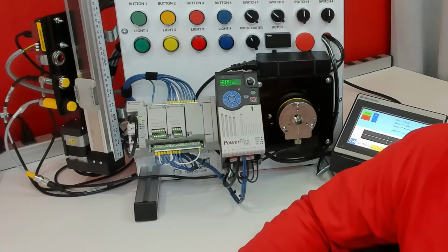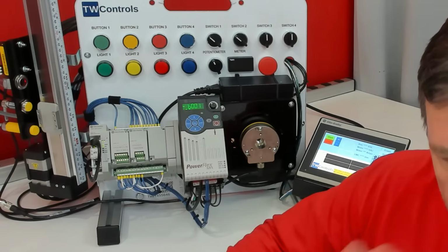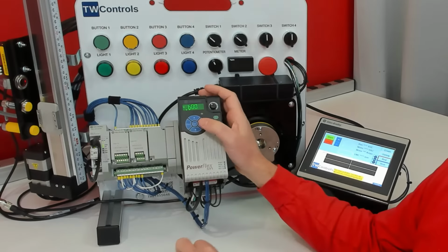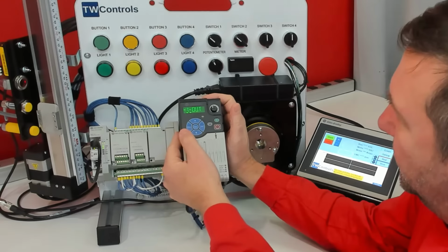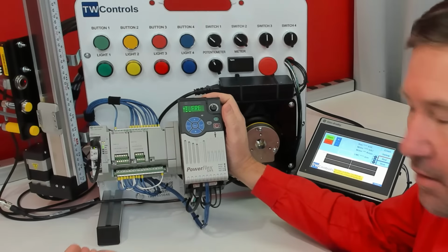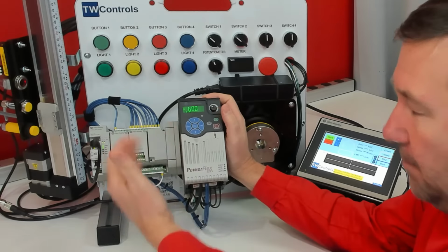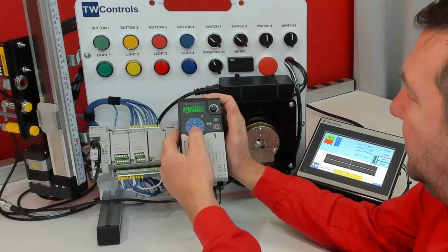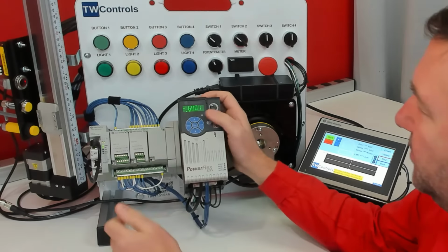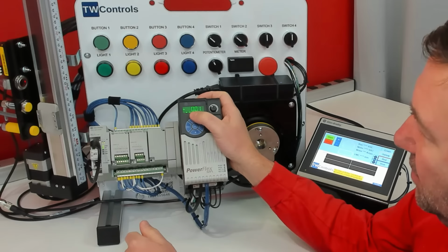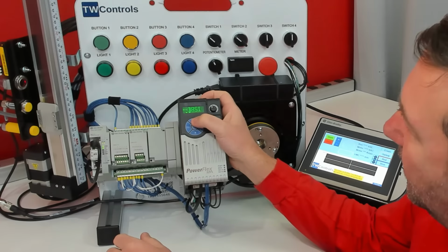And then let's talk about the drive control. So first, what we're going to do is, depending on where you're at, and honestly where I've been with this, I'm going to reset this PowerFlex 525, the main operating parameters to it, back to its default. So I am going to get the B flashing. I know it looks like a 6, but that's a B. And I'm going to hit the up arrow.